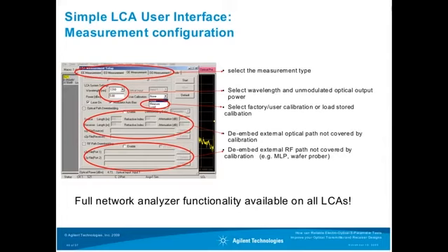de-embedding features, for instance, like de-embedding the wafer probes, the optical probes in an optical path de-embedding. But more importantly, you can also very simply use the S-parameter files for electrical probes, like a minimum loss pad or a wafer probe, into this setup, and then the Lightwave Component Analyzer automatically fully de-embeds and removes the impact of those adapters from the S-parameter measurement.